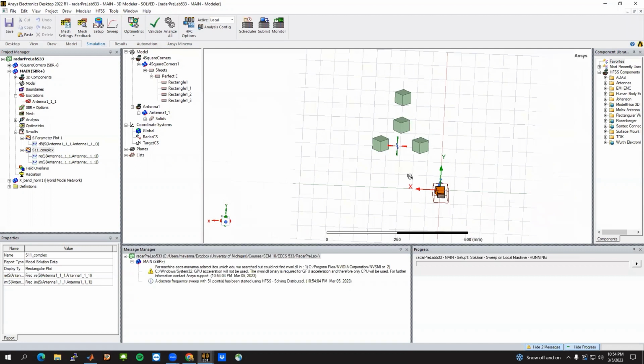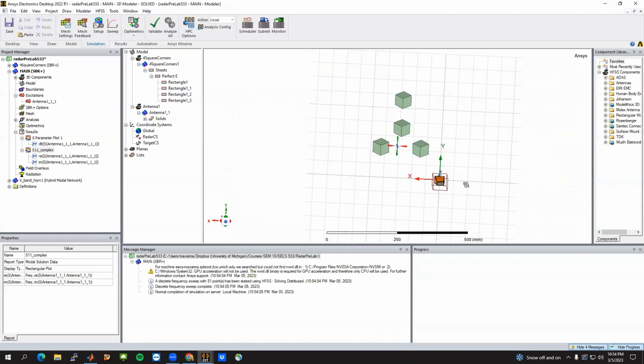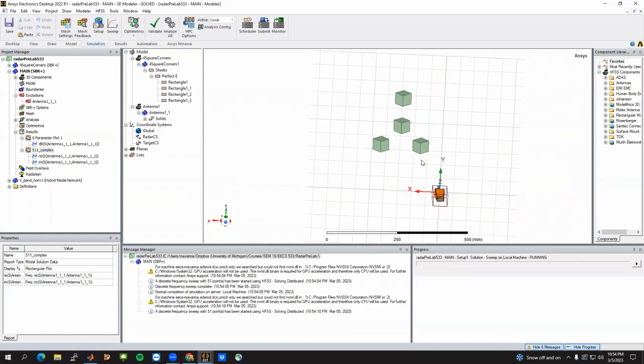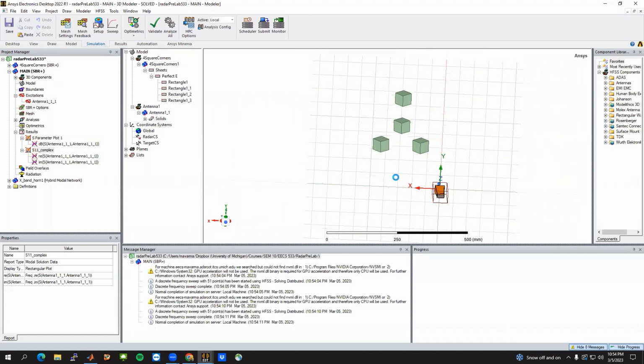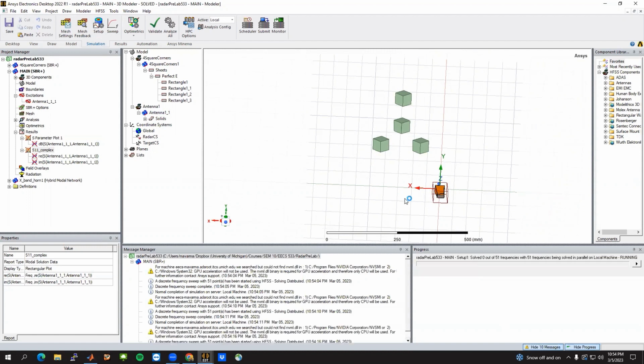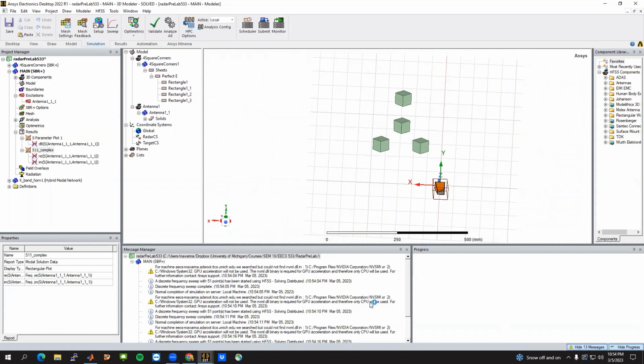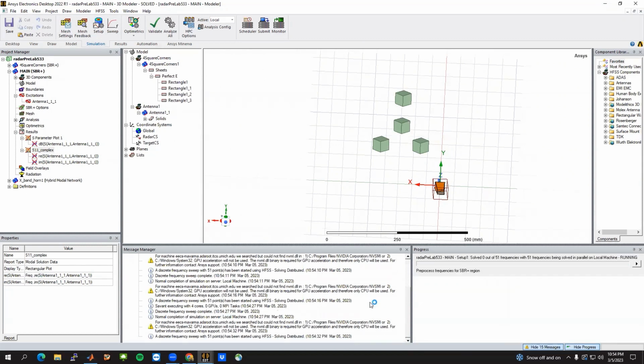It's going to solve for this location, change to a new location, solve for that, change to a new location, and keep doing that. This will take some time, maybe a couple of hours, because there are so many data points, about 21 by 21. So that's over 100 points. That's why you probably don't have to run this. I'll actually run this for you, save the data, and upload it to Canvas. So you can just use the measurements for your SAR processing. So I'm just going to stop this.